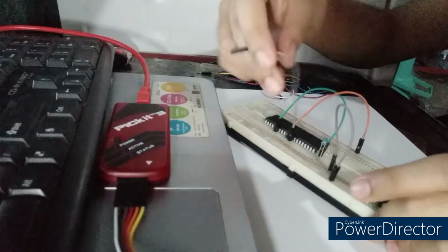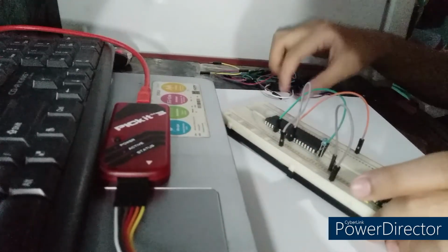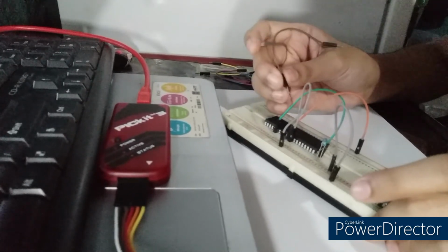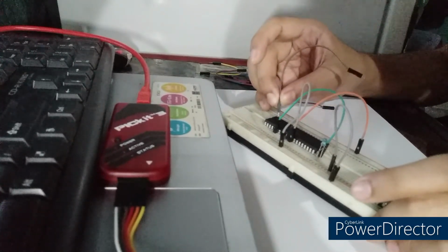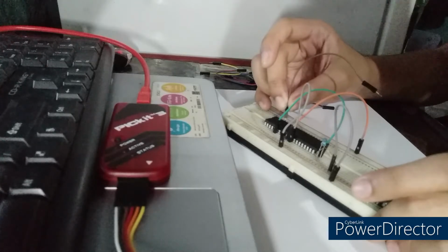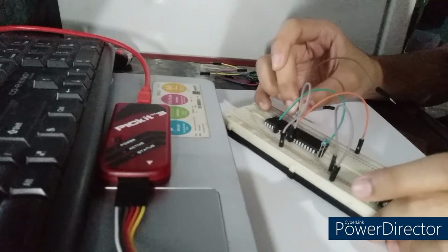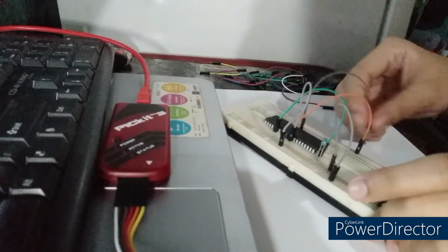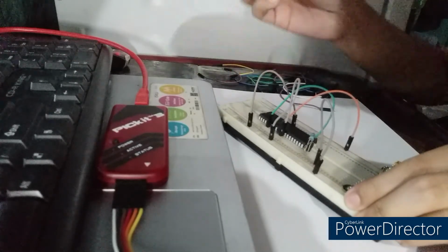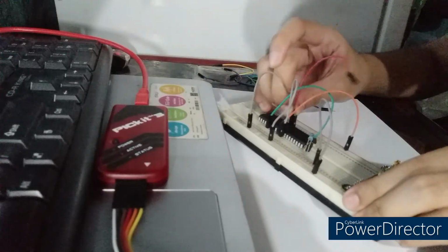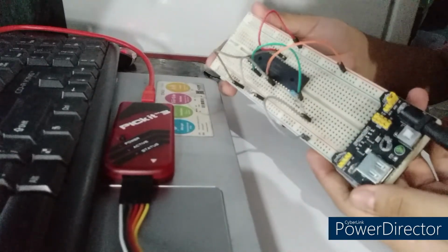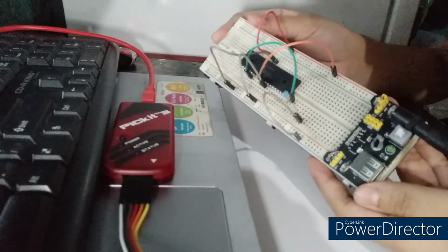So our VSS and VDD on the other side of our IC should be connected to the ground and the voltage supplied as well. So our VSS is on the 31st pin. So from here, 40, 39, 38, 37, 36, 35, 34, 33, 32, and 31. So this should be connected to our ground. And then our 32nd pin of our IC, which is the VDD, should be connected to our voltage supply here. So this will be our circuitry for our experiment 1.